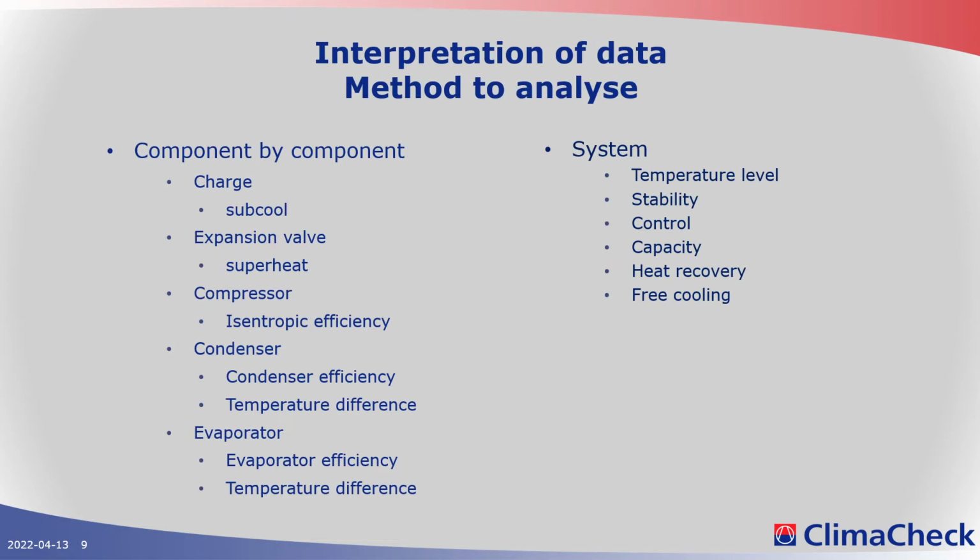Then everybody will build their own method, experience on how they check through the data. Personally, I like to first focus, do I have the right refrigerant charge? Because otherwise everything will be incorrect anyhow. So when I know that my charge seems to be okay, then I check my expansion valve. Then I check my compressor, then my condenser, then my evaporator. So I go through the same sequence every time because it saves me time.